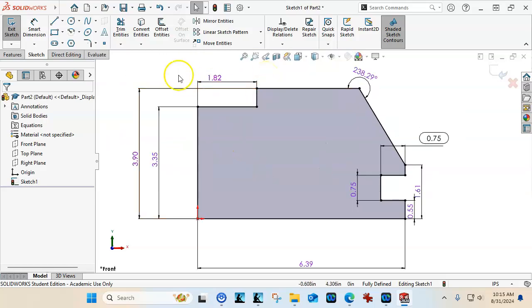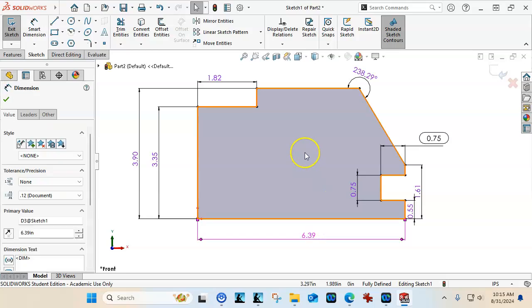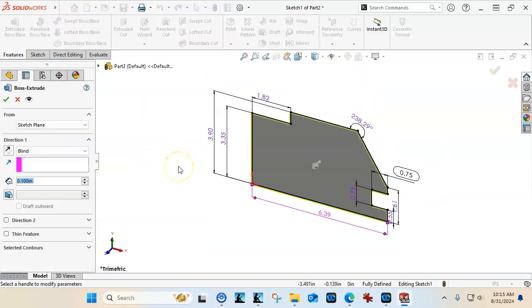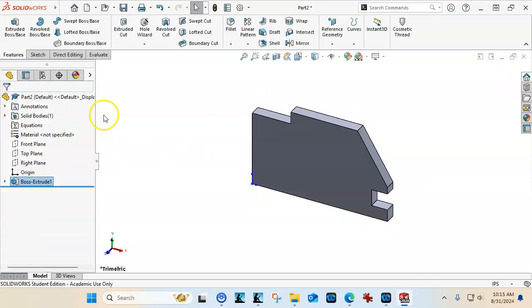All right, so I'm going to go ahead and extrude this. And the advantage here is that adding all of those holes into this base piece is going to make this more complicated than I really want to deal with. So 0.5, I'd like it to go the other way. We'll go ahead and hit OK.